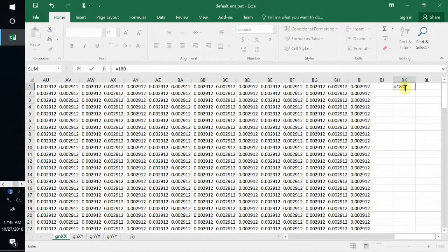So for theta, we have 180 degrees in total, because we are ranging from 0 to 180. That means we're going to have 180 plus 1 points. We have 61 points here. We'll subtract the 1, and that leaves us with 60. And dividing these two shows that we have 3 degrees of resolution. So a point at 0 degrees, 3 degrees, 6 degrees, all the way up to 180 degrees for this antenna pattern input file.